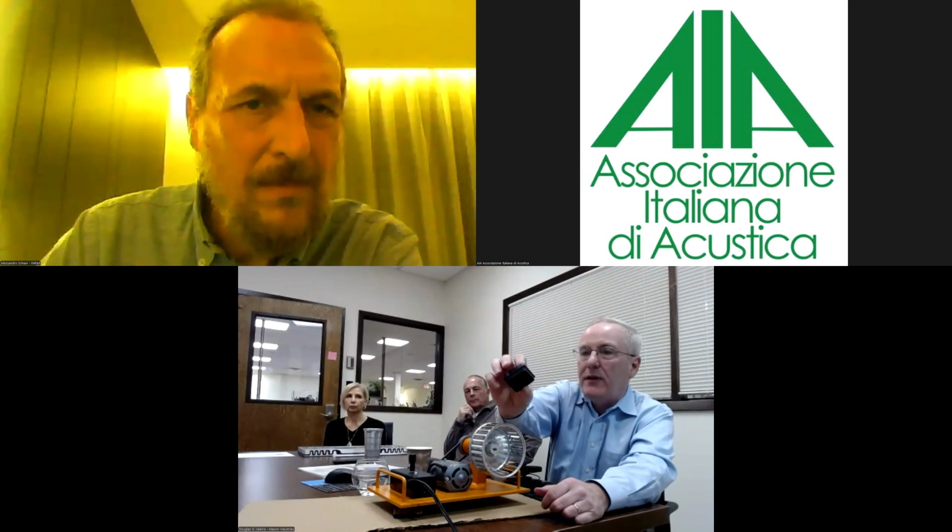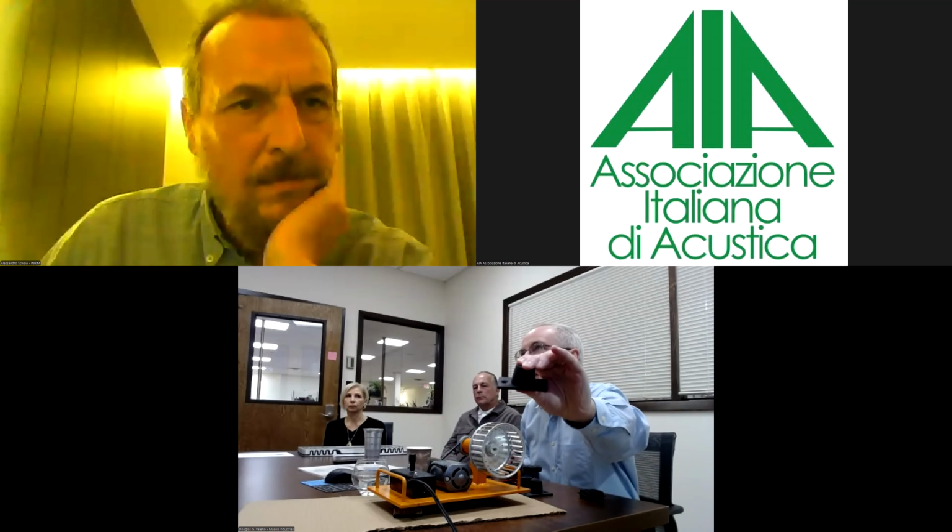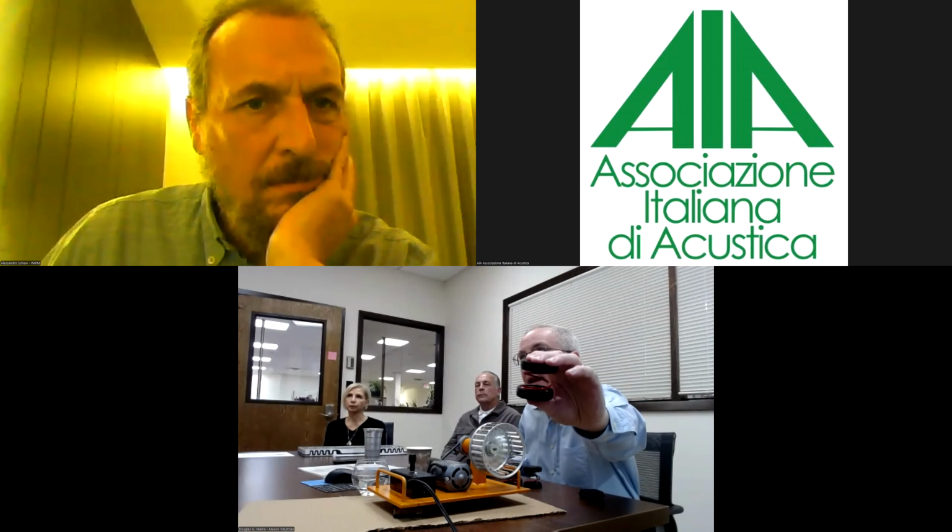A pad that's a little bit better, little rubber pad, is going to deflect, I don't know, 5 millimeters or so, better than the cork. It's like a little piece of waffle. Again, for the purposes of this test, it's going to be underloaded. It's not going to deflect much. But just going through the hierarchy of isolation, what performs better. You get into little rubber mountings. These deflect, I don't know, 8 millimeters or so, if properly loaded, a little bit more deflection. We'll go through all these. And then you get into steel springs. And steel springs are designed anywhere from 25 to 125 millimeter deflection.